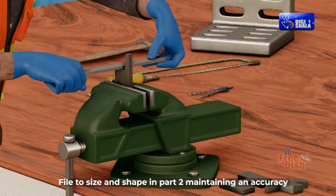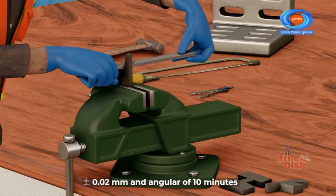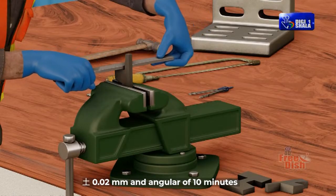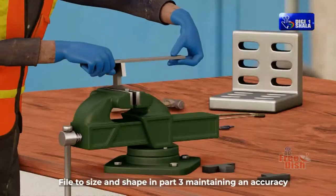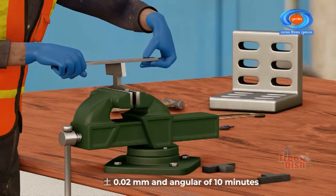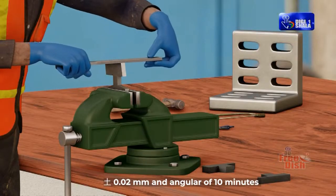File to size and shape in part 2, maintaining an accuracy plus or minus 0.02 mm and angular of 10 minutes. File to size and shape in part 3, maintaining an accuracy plus or minus 0.02 mm and angular of 10 minutes.